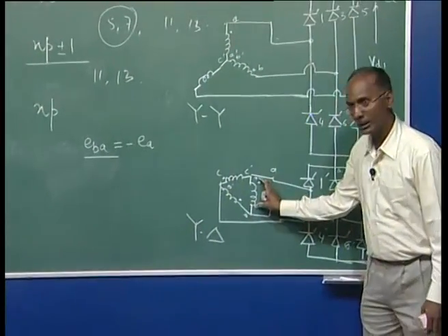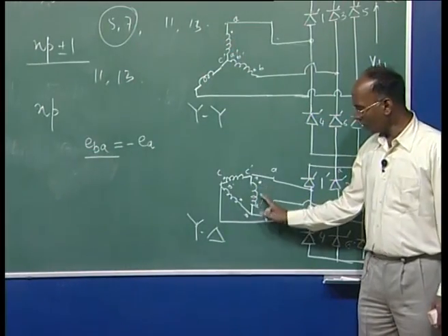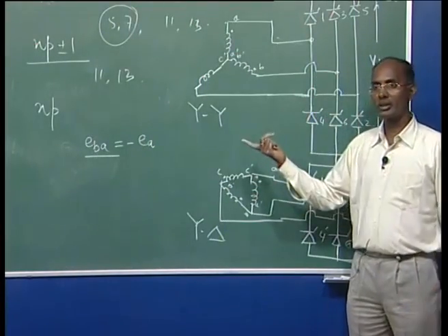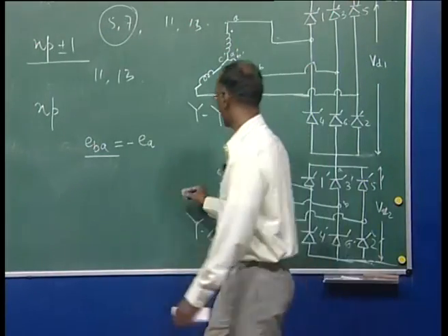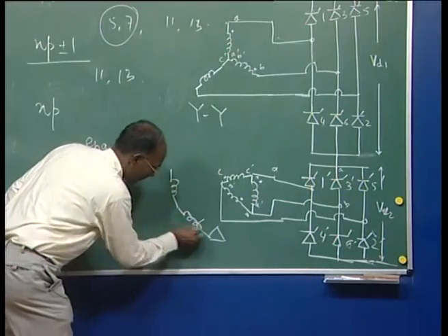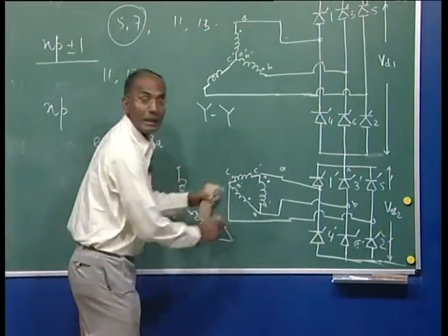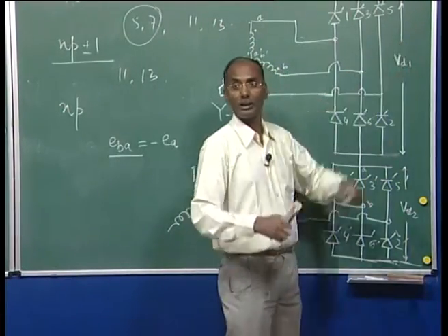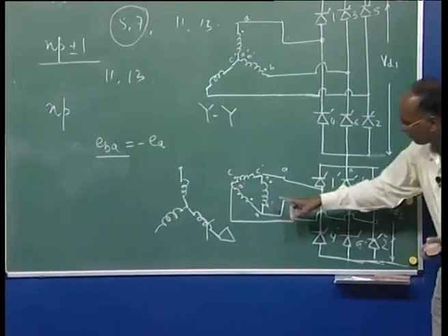The phase voltage here, we are talking about line to line, but this is equivalent to the phase voltage. No doubt, this phase voltage we are going to transform with such a turn ratio that it will be root 3 times the phasor voltage of that side. This side is simply star, as I said. So we take care of this transformation because the magnitude should be the same, root 3 times here and line to line here, then we add. But here we get this as minus.